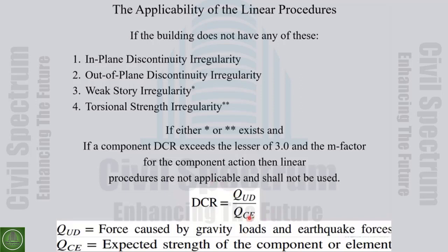Therefore, this is a good measure of the damage in the deformation control parameters, because we just accept damage there. So the linear procedures are acceptable depending on whether the building really gets that much damage. If the building is not that badly damaged, the linear approach is good.